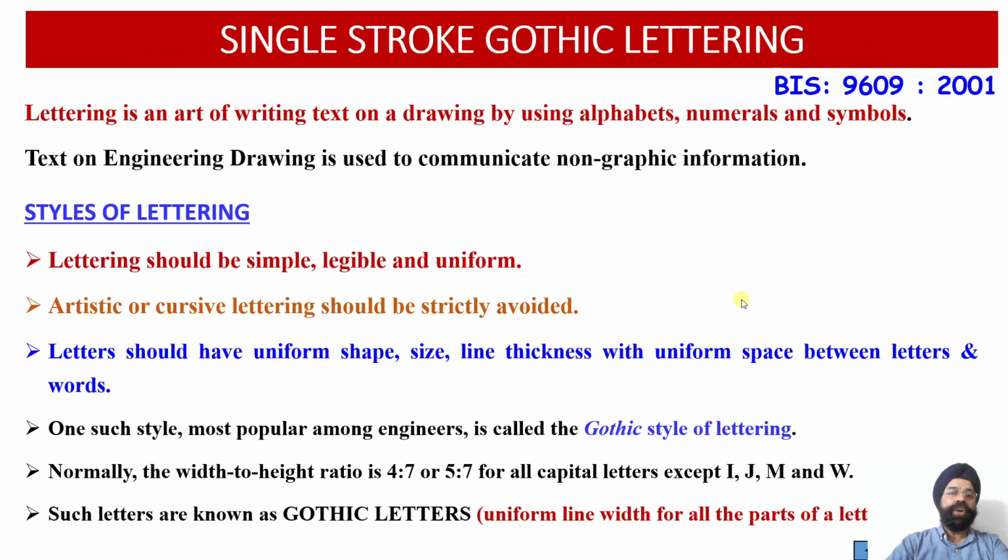Now, when we talk about the Gothic lettering, basically we are using single stroke Gothic lettering as well as double stroke Gothic lettering. But first of all, we need to understand that the putting down of the text onto the engineering drawing is once again governed by the BIS standards, that is, the BIS 9609 2001 standard.